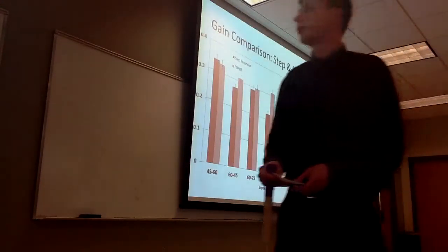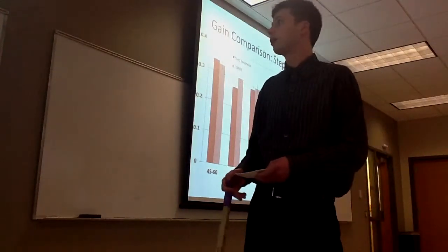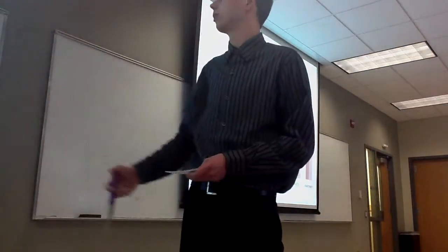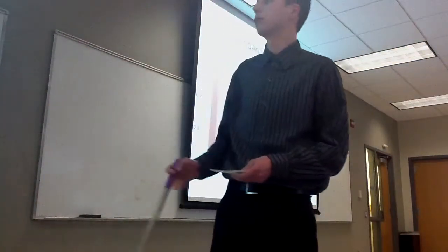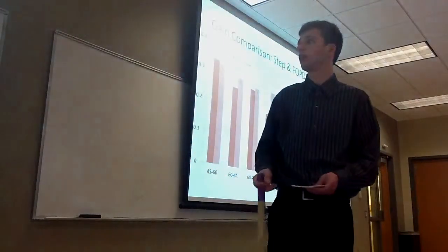This is a chart comparing our step response and our modeling data. The average, you can see, is very, very close. It's very close to 0.3 pounds per minute per percent, which agrees with our steady state operating curve gain.